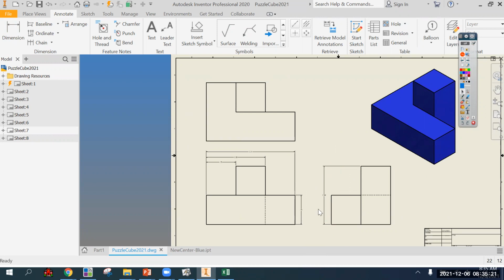You could, of course, do top to bottom every time something happens, but just stick with me and you'll be fine. I think aesthetically having the dimensions work building up tends to look a little tidier, but you can still meet all the rules by doing top to bottom. So the only other dimension is depth, which is front to back. Depth is either here on the top view going this way or on the right side view going that way. That is the depth dimension.